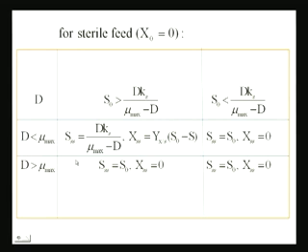Now, if either of these two constraints is violated, then what you end up having is a trivial solution, as you have over here. All these are trivial solutions because XSS is 0 and the steady state concentration of the substrate is the same as what you put in. The best way to remember this is that these two constraints have to be satisfied. If they are, then in this space where both constraints are satisfied and intersect, you get this solution. Anything else, you get trivial solutions.